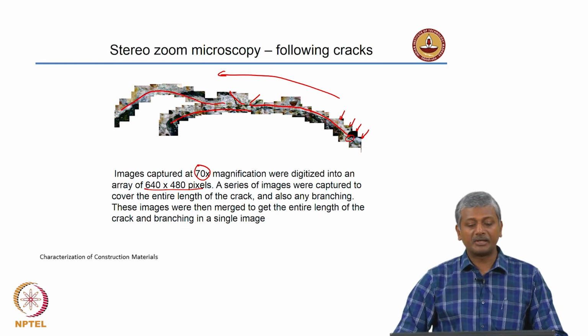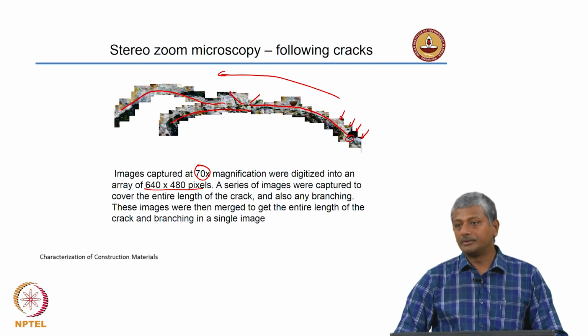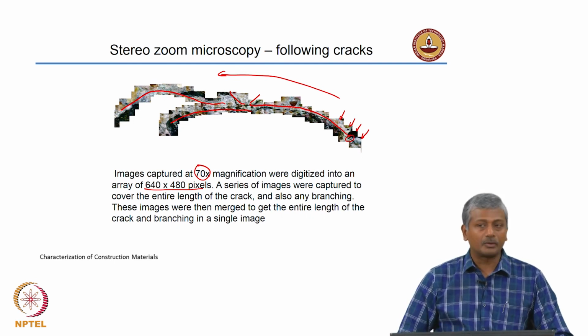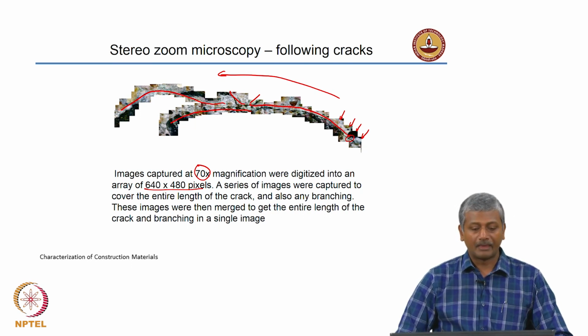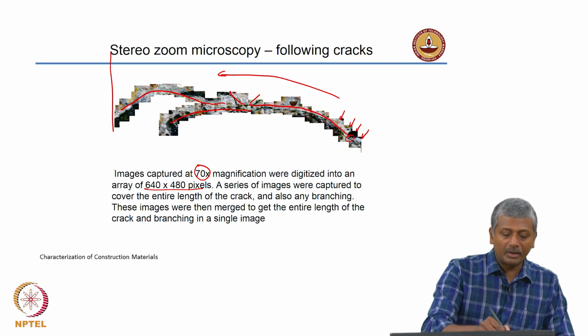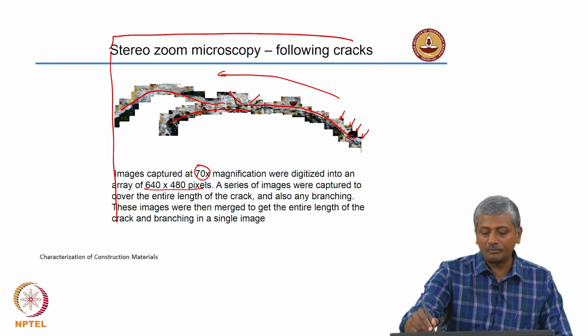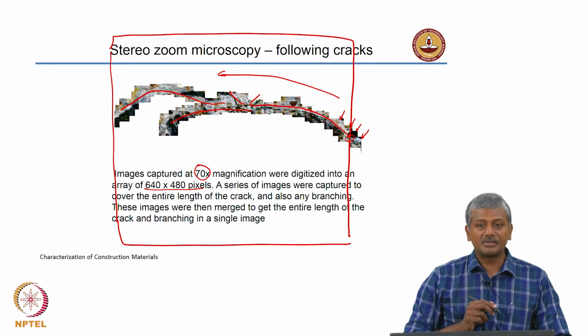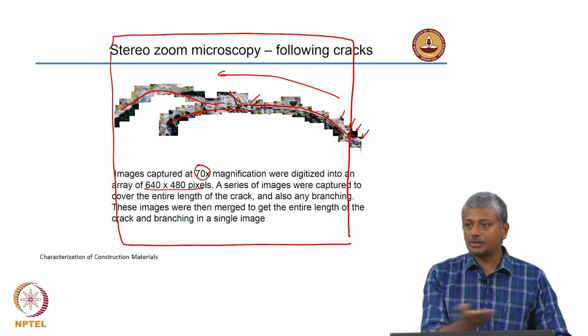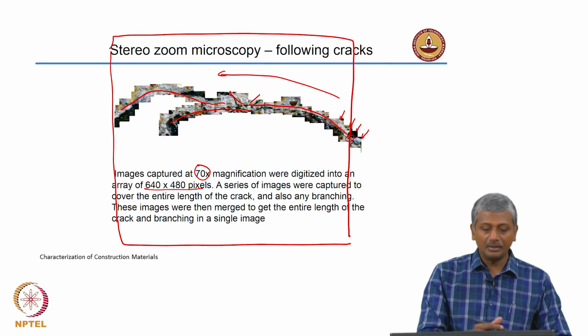That is approximately the path taken by the cracks. So, the idea was, if you image across so many different locations, you now have an extent of how far this crack is going. Now, mind you, this is all part of one large specimen, a 50 by 50 millimeter specimen. We are just taking one particular horizontal section and imaging it in the microscope.